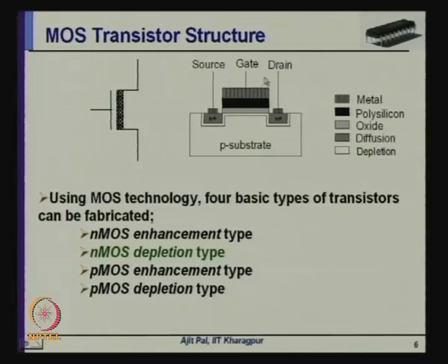And you may ask, in this particular case, how do you really stop the flow of current? What you can do, you can apply a negative voltage to the gate, and obviously, if you keep on increasing the negative voltage on the gate, then it will gradually deplete this region, that means clear the region of charge carriers.